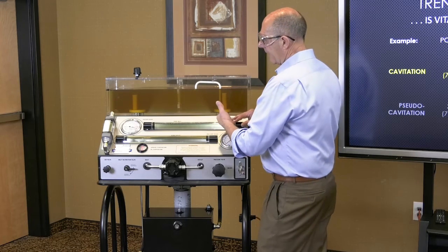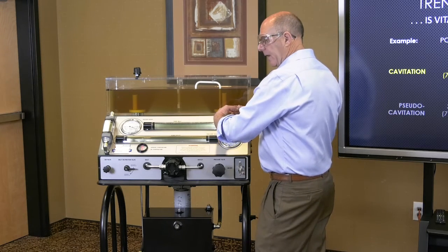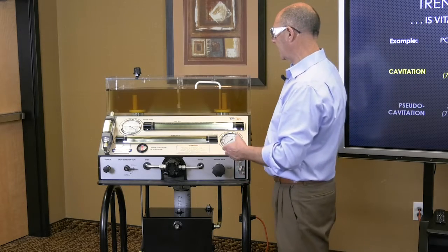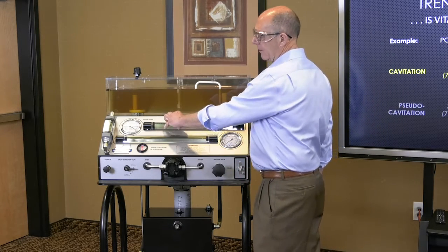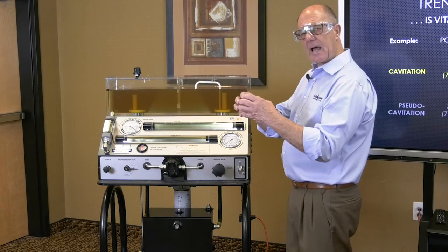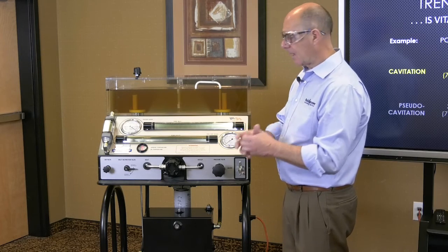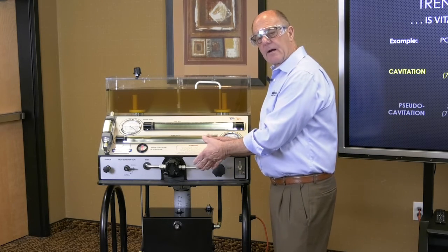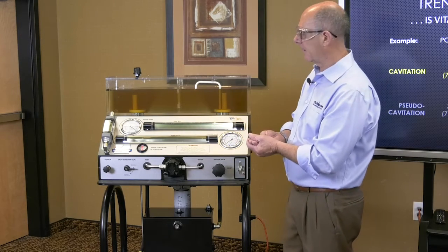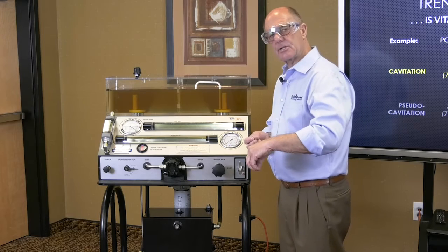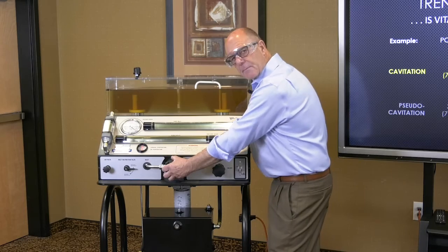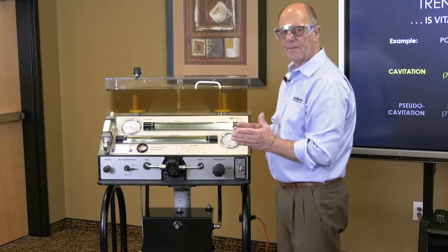What happened was, as the oil was subjected to a vacuum, or let's say a higher than normal vacuum, the dissolved air came out of the oil, it went through the pump, and the gaseous cavity imploded. The air then went back into suspension, so you can no longer see it in the oil. That is cavitation: the formation and collapse within the pump of the gaseous cavity within the liquid.